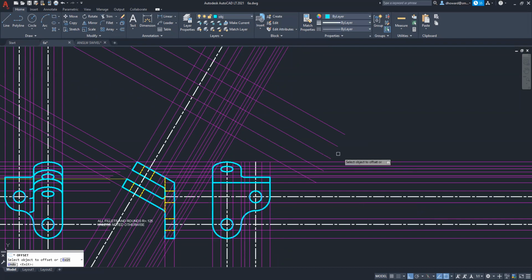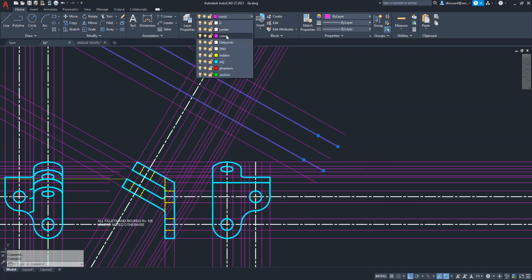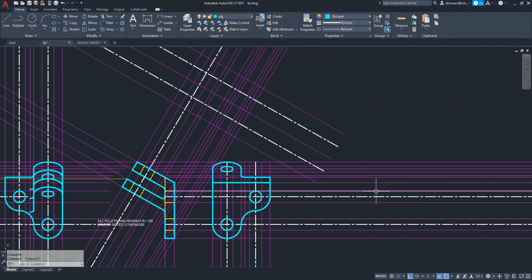We would also have the, and these are the center lines. I'll mark those now. So those are those center lines. We can offset each one of those, the diameter of the holes. So I'll do that next. O, enter. And the hole diameters are 5/8.